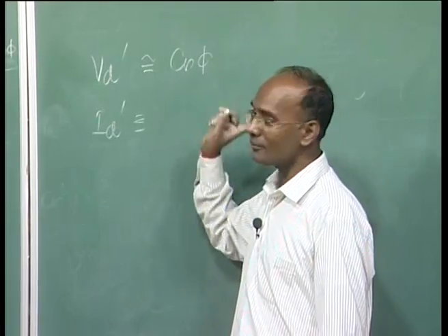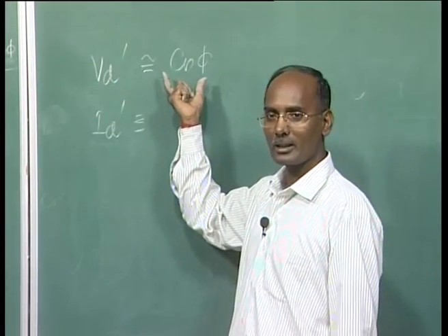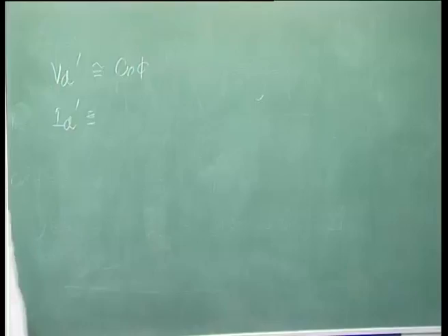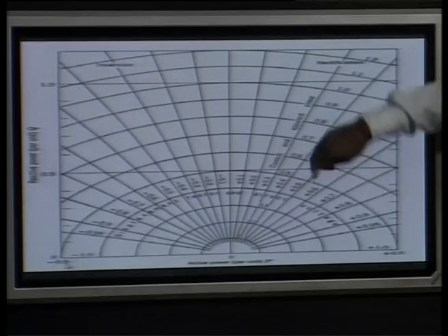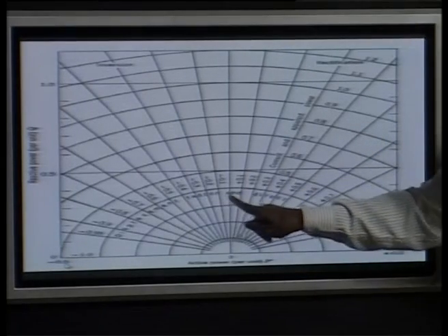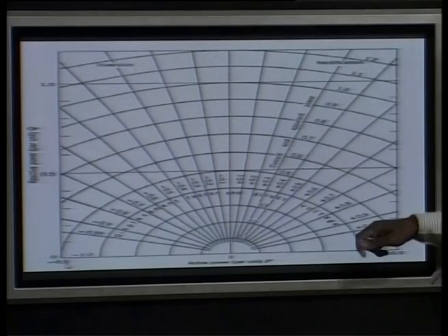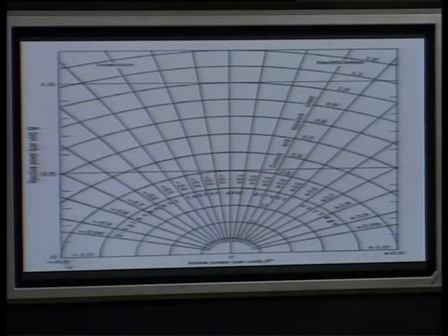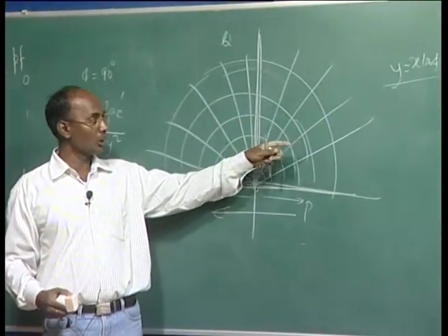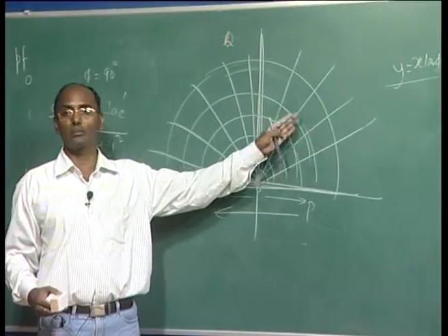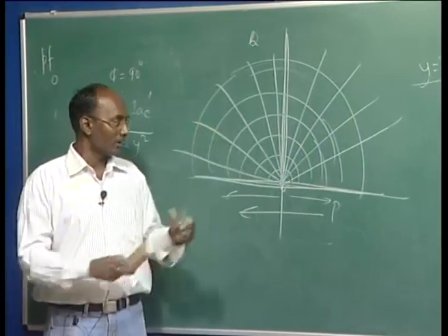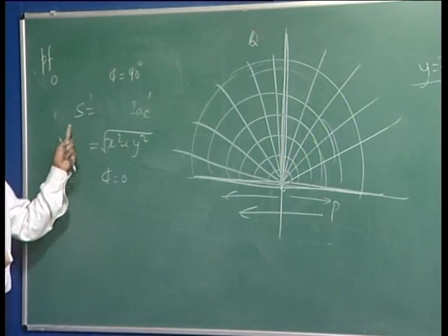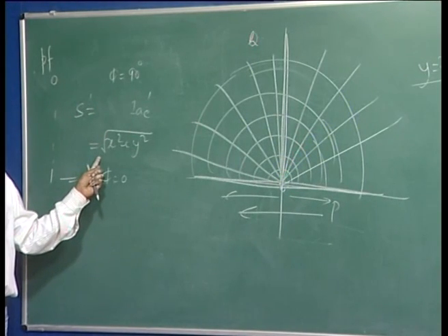So you can see this is cos phi, and this is nothing but a characteristic similar to your displacement factor. That's why you can see written on these scales the displacement factor and the direct voltage. So these slopes are showing your displacement factor as well as the direct voltage in per unit. These circles are showing your apparent power and your current.